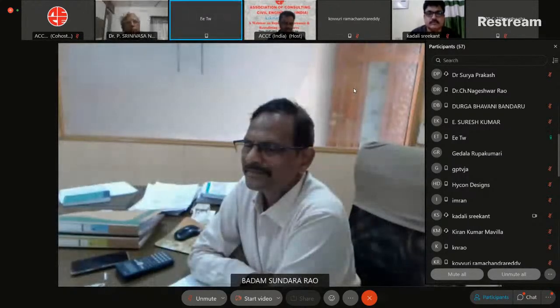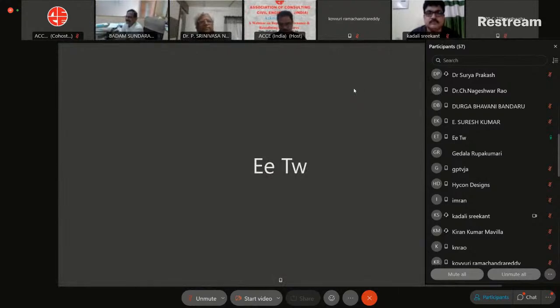I'm a postgraduate from JNTU Hyderabad. I want to say something about brick masonry. To avoid maintenance of the structures, mainly nowadays, in the execution of masonry, no one is following the bonds, Flemish bond or English bond or anything else. Also the bricks are of very, very poor quality. The surfaces are not even, they do not give a ringing sound, and sharp edges are not found. So in time we face problems of plastering, painting, whitewash or anything.